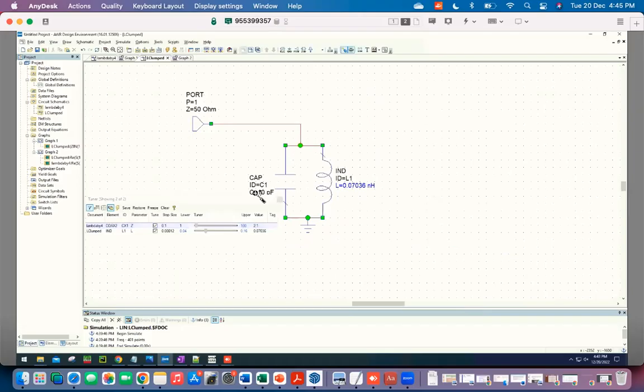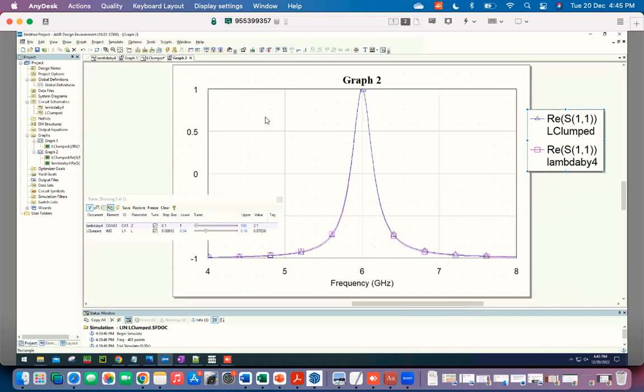drawn here. So remember that by the fact that the frequency is fixed, the effective L has to be the value I have chosen here. Otherwise, the frequency will not match. But this is completely impractical. 2 ohm transmission lines basically don't exist in most situations. It is not impossible completely to make it, but it's highly impractical, because the kind of capacitance per unit length